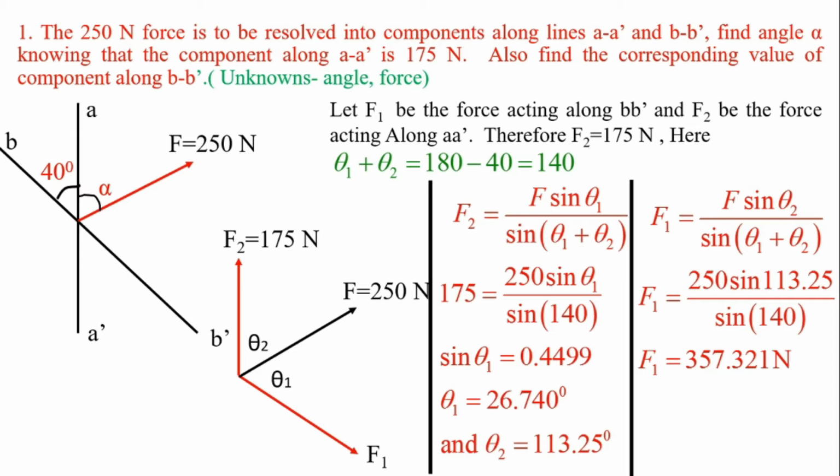In this way, first you should identify the problem. The problem is related to skew resolution. If the directions are perpendicular to each other, then the resolution is called rectangular resolution, and simply using Fx equal to F cos theta, Fy equal to F sin theta, one can resolve the force. But here the directions are non-perpendicular, and hence we have to use the concept of skew resolution.